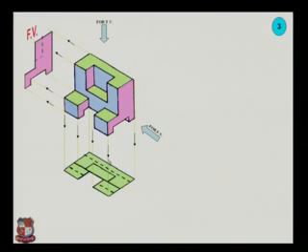Now considering the dotted line, this dotted line is the line of this portion of the slot in the downward direction of the pictorial view, and the same for this dotted line. This is the slot when we see from the top view, which is hidden from the top view.